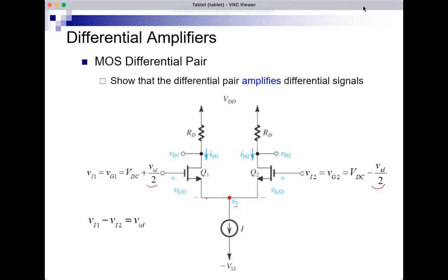So if this is a virtual ground, when the two inputs are differential, this here is virtual ground. Same here. So virtual ground, not a real ground, not hardwired to ground, just a virtual ground. No signal appears there when the two inputs are fully differential.